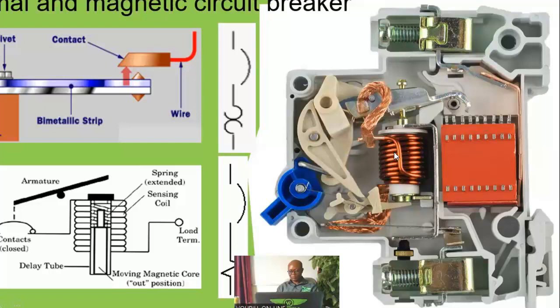the circuit breaker. So you see that because of this magnetic device that we have in this miniature circuit breaker, once there is an overcurrent, like short circuit current, okay, not overload now, you see that it will just trip instantaneously. Are we getting it? As it sees it, the magnetic strength will be strong enough to push this and then release the latch, and then the breaker will trip. So a combination of this makes the breaker to be complete. So most of the breakers that you will come across, especially the miniature circuit breaker, even the molded case circuit breaker, they have both elements in them. And that is why they are referred to as the